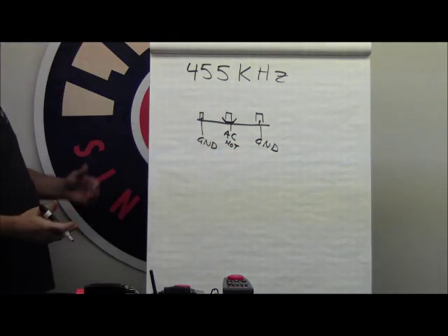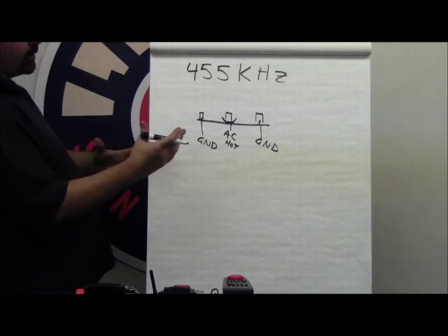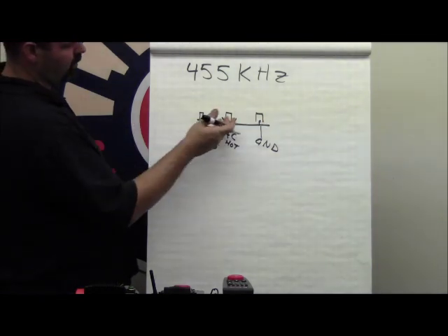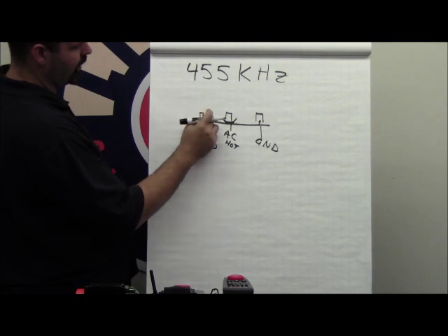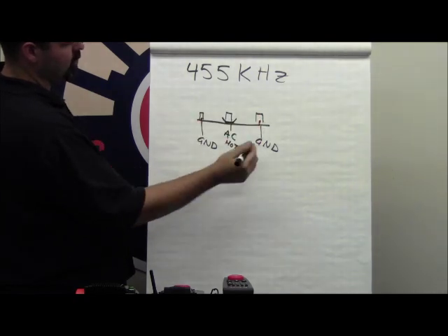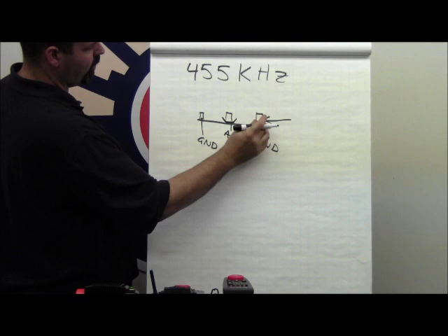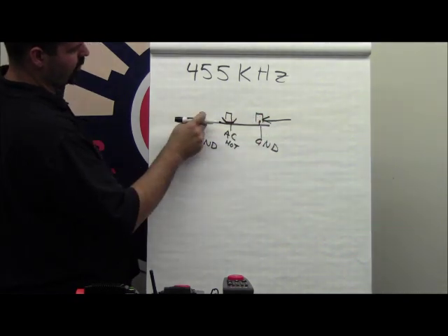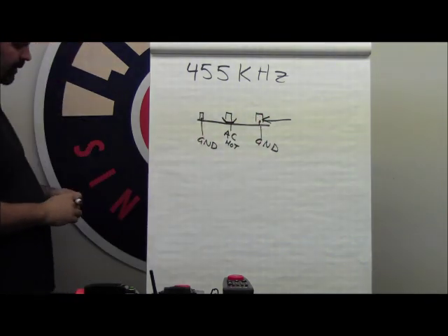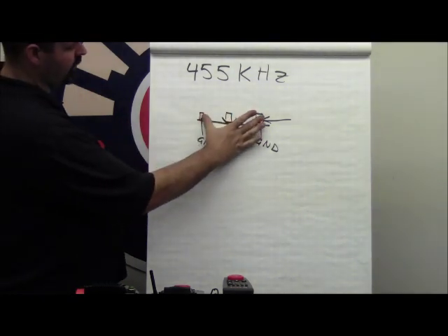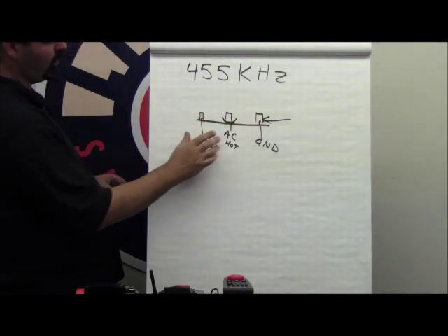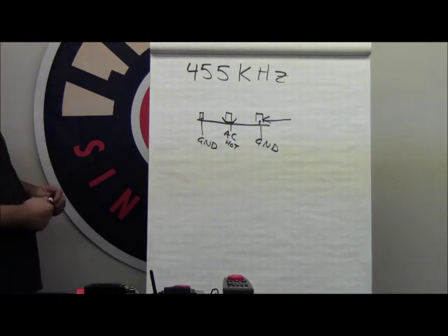On Lionel FasTrack, even though you've got a plastic roadbed, on the underside of the track there's a metal connector that connects both outside rails together. So when you put a wire to this rail, it automatically transfers the current to this rail. The center rail is always hot, so it's not affected by these 2 rails at all. Well, when it is, you've got a short circuit.